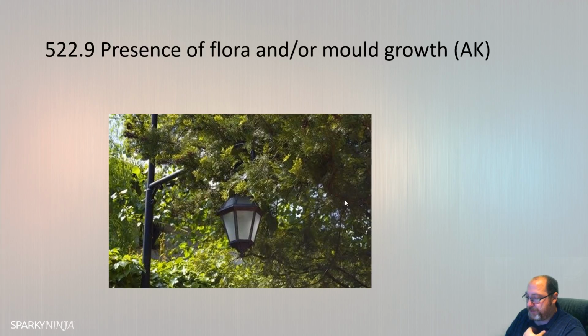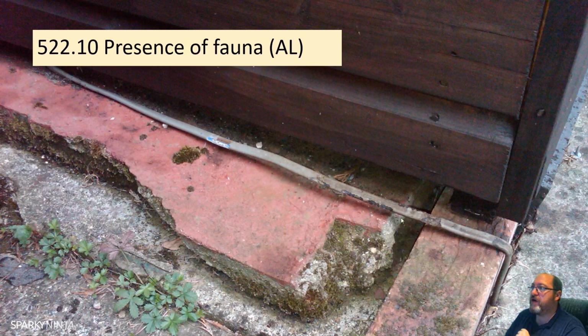Then you have fauna. So you have hazard AL2. It will be selected with suitable mechanical characteristics. So if you're in a caravan park and you've got this little twin and earth feeding your shed, then this needs to be replaced with an armoured cable and maybe installed in a way that's going to avoid any rodent or pest impact. Similarly, I've also seen street lights or lampposts filled with ants nesting, and they can be detrimental to the wiring in those as well. So you've got to select a suitable wiring system, etc.